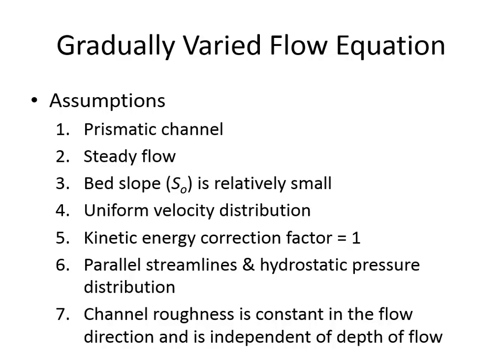But most of the time, even with something as steep as a 10% slope, the vertical depth and the flow depth are about 0.995 the same. So we'll apply this only when the bed slope is less than 10%, which is plenty steep.